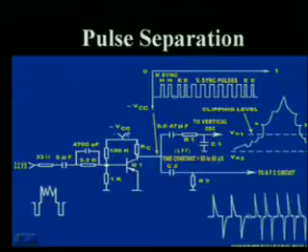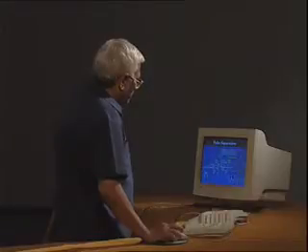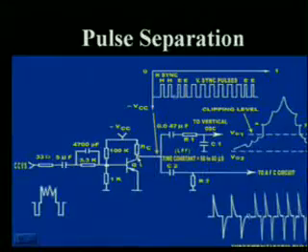If we see here, this is the sync separator stage, which gets the CCVS, means color composite video signal. After automatic biasing, this separated sync is available at the collector of this transistor, and the shape of this separated sync is this one, which has both horizontal and vertical sync pulses.